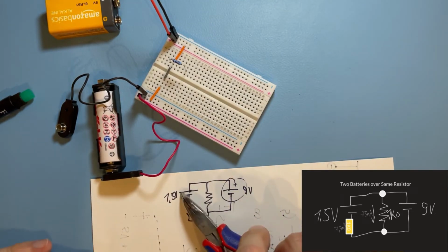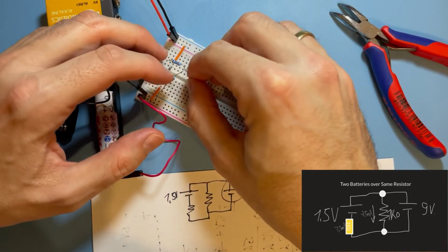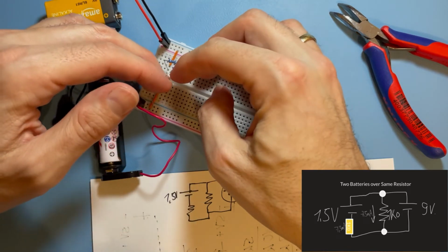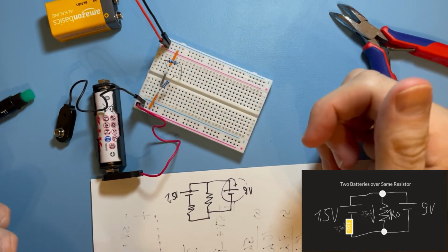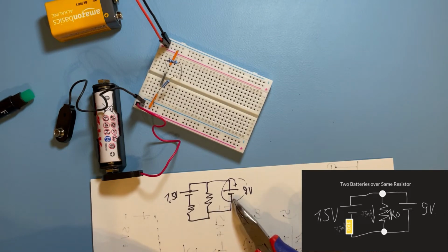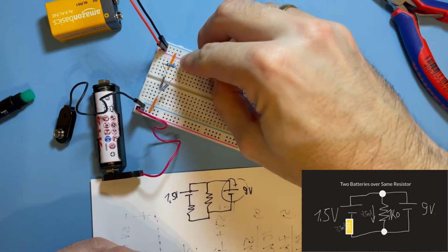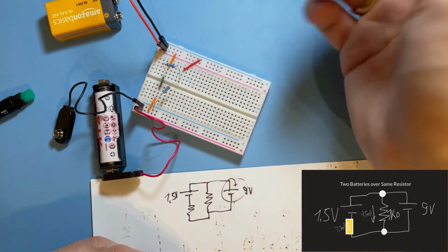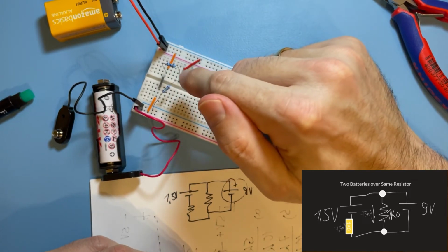And then we have to connect the minus of the 1.5 via resistor to the other resistor end down here, to the other resistor's far end. So we're set up this way, and then the last thing we do is to connect this joint to the ground of the 9-volt battery. We connect that to the ground of that, and we're all set.